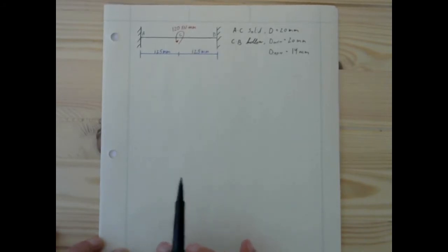If we're seeking to solve for the reactions of an indeterminate structure that is a torsion bar, what we're going to find is that torsion shares some characteristics with axial loading. It of course shares characteristics with moment. It is moment, but about a different axis than the other moments we've thought about in the past. And of course it's going to share attributes with shear because, as we've discussed earlier, the stress it's going to be experiencing is shear. So it's going to have a combination of all the things that we've talked about in the past going on.